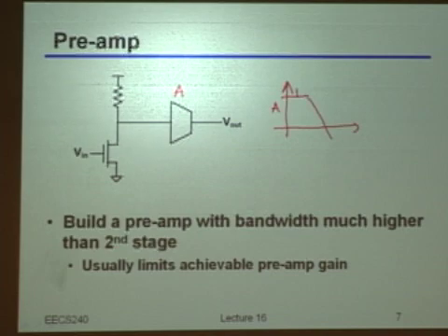But I need to take care that the second pole that I introduce is far away from the crossover frequency, so that I will most probably not perturb the crossover frequency too much. Then the second pole starts far away, and so I still have a good phase margin. So I add another preamplifier, and this is a way of taking care that the chain is still stable, right?